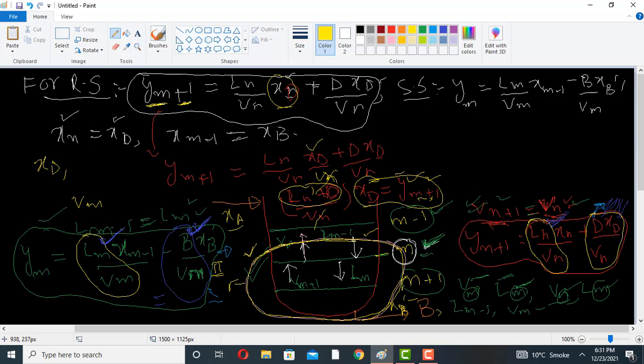So this is the x, and this y is also xD, because the coordinate of a point is (x, y). When we put xD in place of xn, yn plus 1 becomes equal to xD. So y and x become equal. This is one point on the rectifying line, and this is the slope of the rectifying line. This is the y-intercept of the rectifying line.